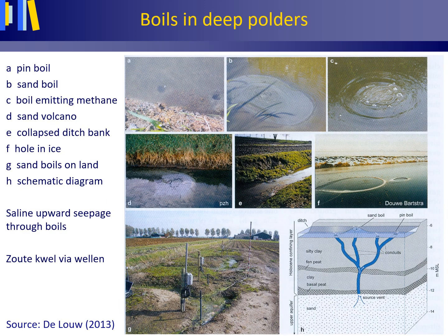Preferential pathways for upward seepage are especially evident from this picture, also taken from the PhD thesis of Perry de Lauw, that shows different types of boils. In Dutch we call these vellen in deep polders. A pin boil, a sand boil where sand is transported upward with the water flow, a boil emitting naturally occurring methane, which is, as you are most probably aware, a most potent greenhouse gas in the Earth's atmosphere, thought to heavily contribute to the enhanced greenhouse effect, versterkte broeikaseffect.